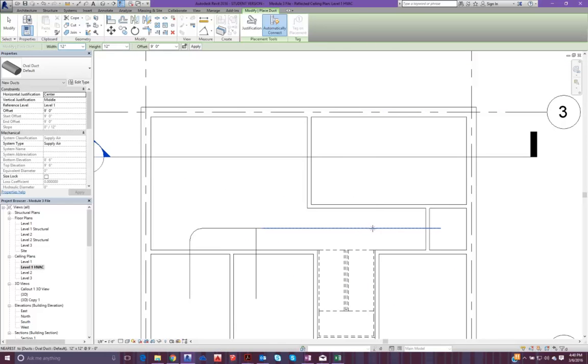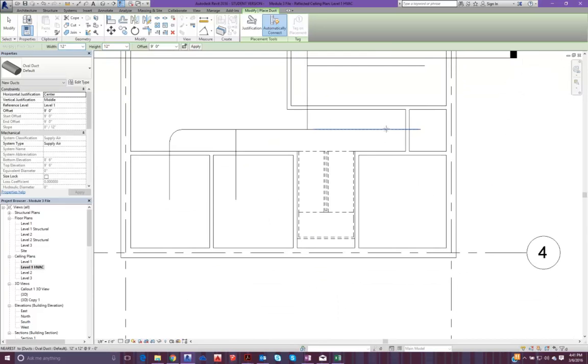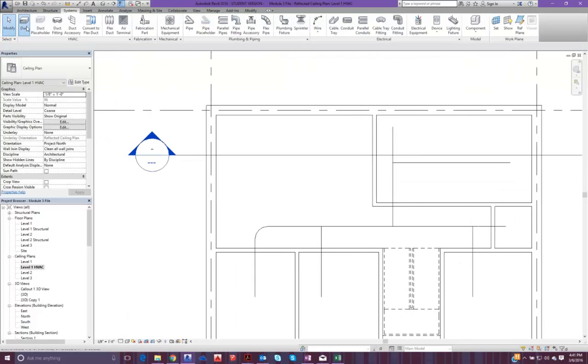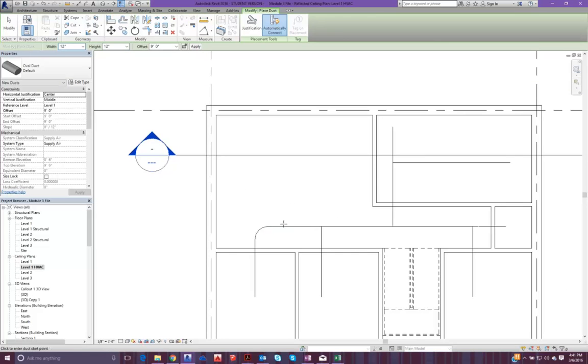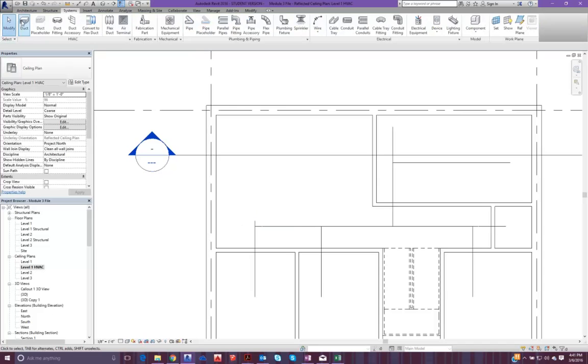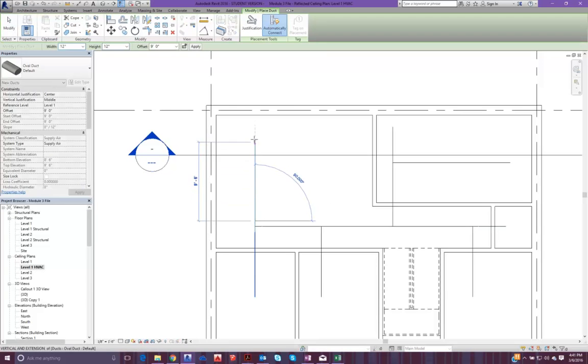Now we'll go ahead and place a duct here in this room, and let's say we have a line at the front here. Let's say this line goes ahead and goes in the middle. And let's go ahead and put some ductwork in the bathroom. And we don't have any in the reception room. So what we're going to do, we're going to go here, hit this plus button again, make that into a T, and we'll connect it right here.